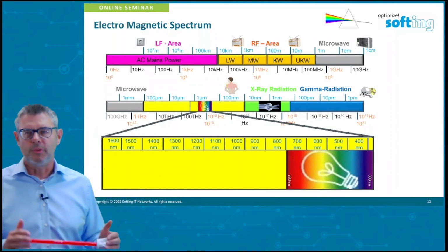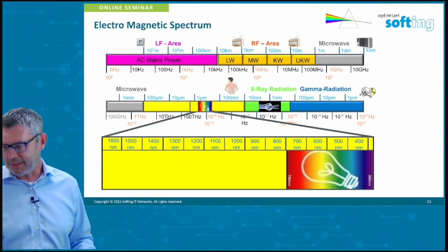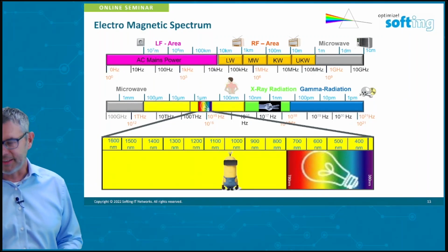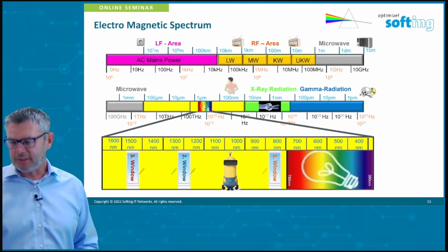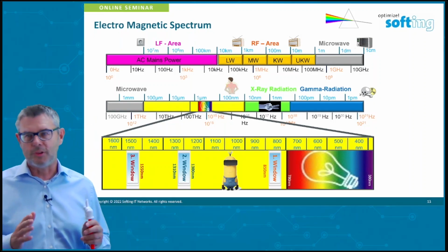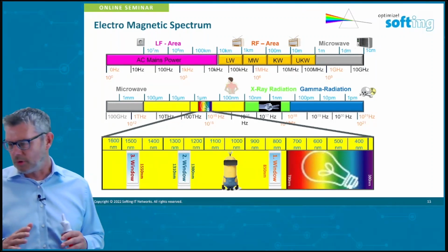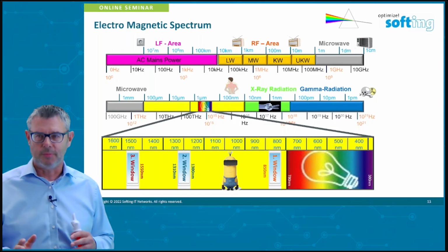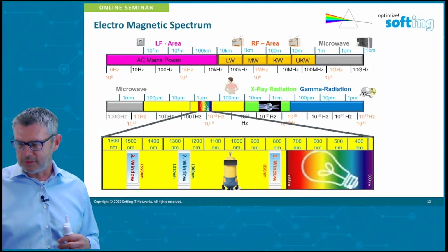No, we don't. We are using infrared light, which is above this level or below this level. No one can see this light, so it's infrared definitely. And we picked three optical windows out of this electromagnetic spectrum which we use for data transmission. The one is around 800 nanometers, the other one is around 1200, 1300 nanometers, and the third one is around 1500 nanometers. These were the basic start of the windows used for data transmission.